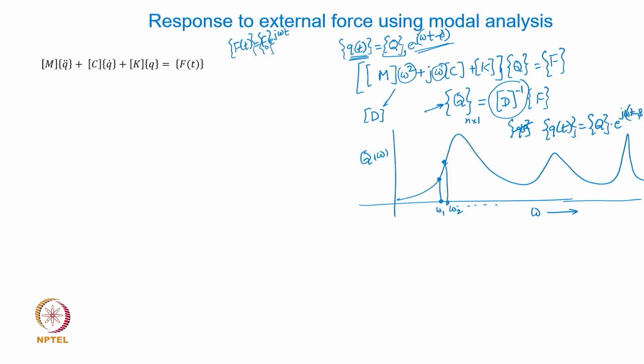So, in the inversion process, I will have to do this inversion every time for every new frequency of excitation. To get this entire response spectrum, the response values at all the frequencies of interest, each time I have to invert this entire matrix. And imagine that this matrix is for, let us say, 5000 degrees of freedom. Every inversion is going to take a hell of a time.